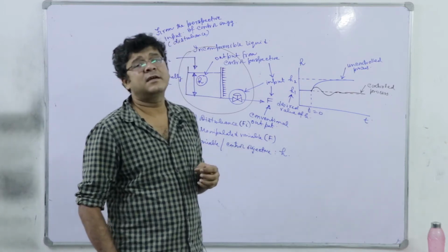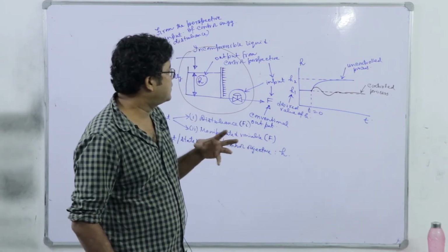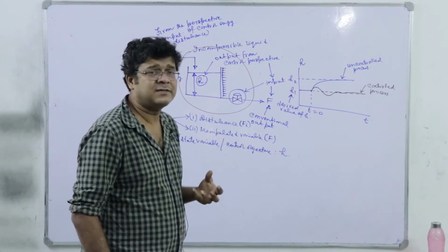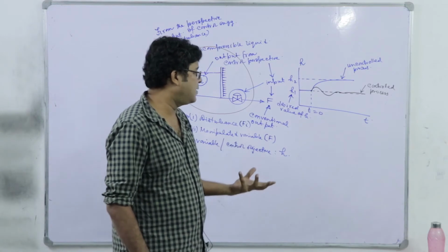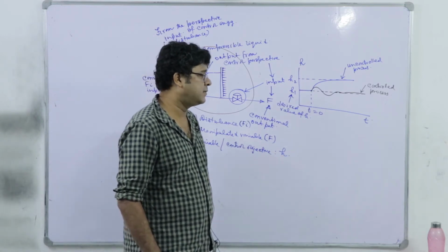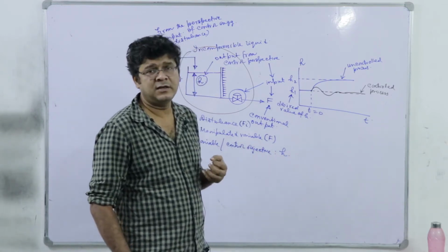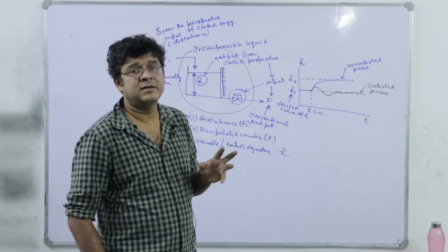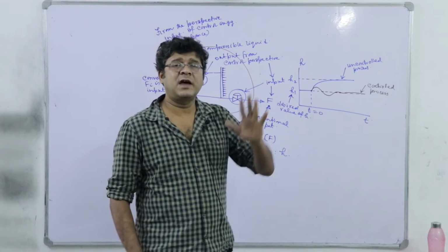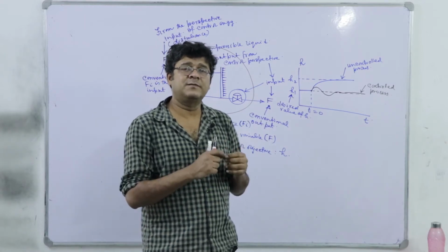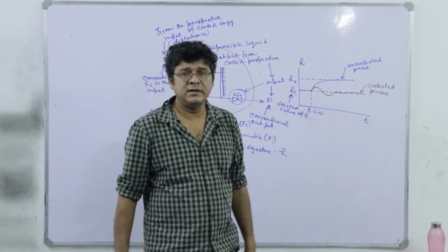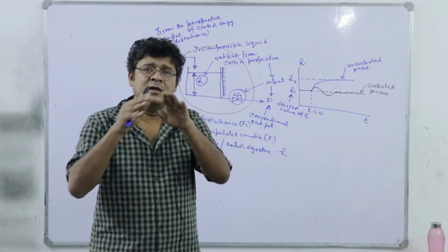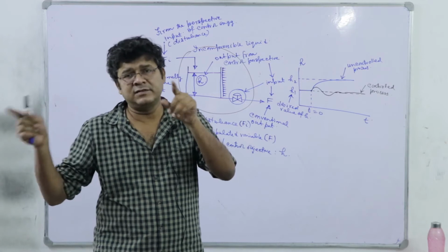Think of this, which is specifically true in case of batch reactors, where we are processing or synthesizing some ceramic materials. And in ceramic materials, what happens? It needs temperature cycles. Over the first 5 hours, the temperature must increase from 30 degree to 600 degree. And we should heat the material at 600 degree for another 3 hours.